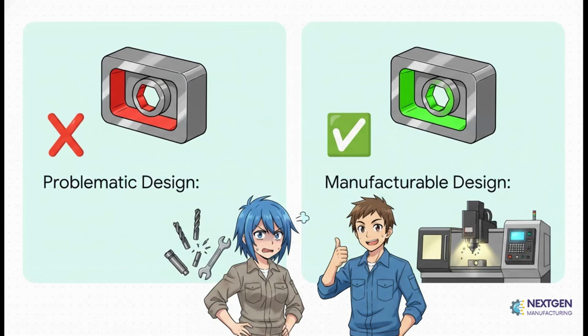And look at this. This is it in action. On the left, you've got a machinist's nightmare. On the right, a part that's easy to make. See the changes? The sharp corners now have a radius that a standard tool can handle. The holes are standard sizes. These tiny tweaks don't really change how the part works, but they make it way cheaper and faster to produce.